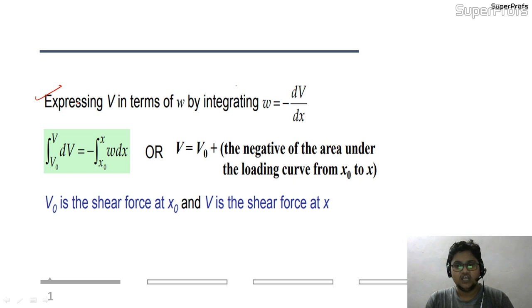It is reverse, friend. Whenever you are going from lower side to higher side, that is from the loading diagram to bending moment diagram, what you have to do is you have to go on finding the area, and whenever you are coming from top to bottom, that is from bending moment diagram to the loading diagram, then you have to differentiate the results in each step.